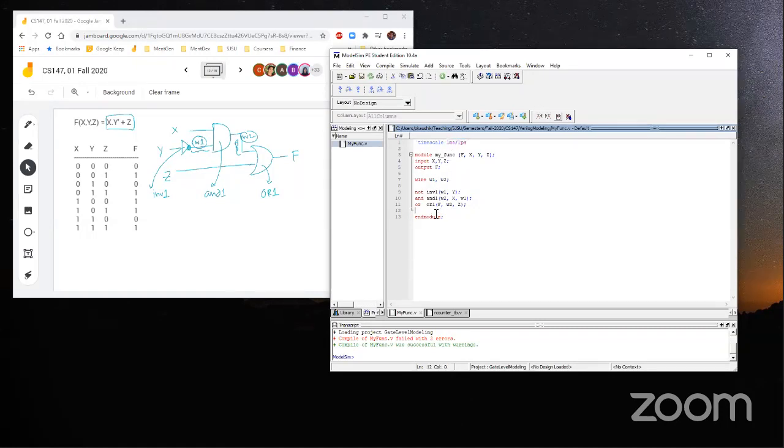This part means that if I do a time delay like #5, that means it is 5 nanoseconds. So the unit is coming from here. And this precision is internal to the simulator setting, how precise you would be from the timing point of view of the digital circuit. I think 10 picoseconds is better, because if you make it lower, like 1 picosecond, simulation time may be longer. For a smaller circuit it doesn't matter; for a bigger circuit it does. So let's see. Yeah, this is successful.